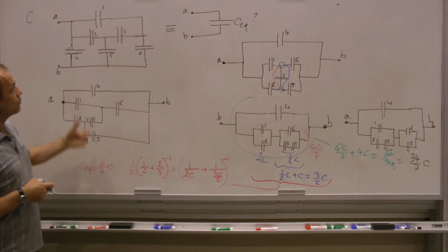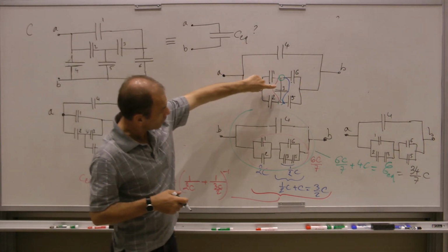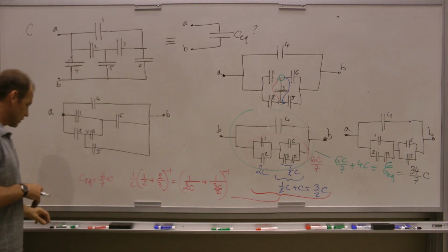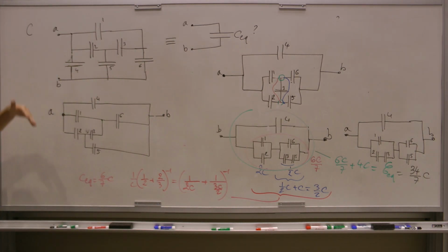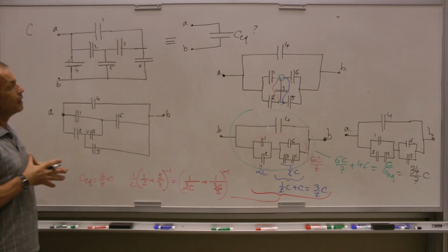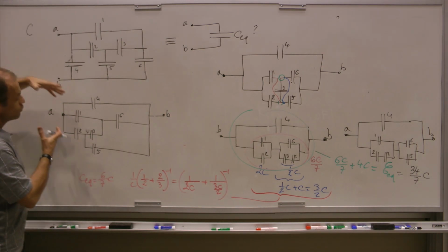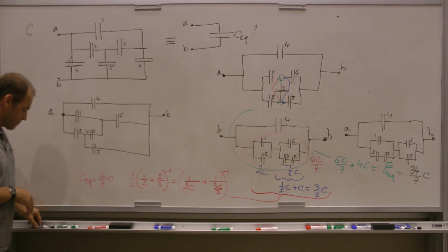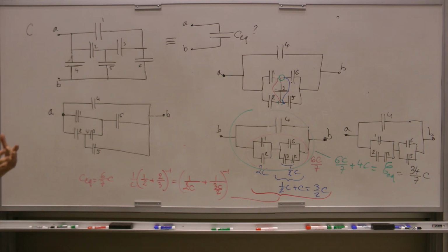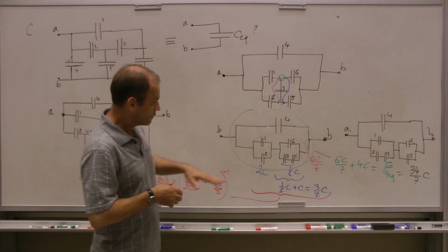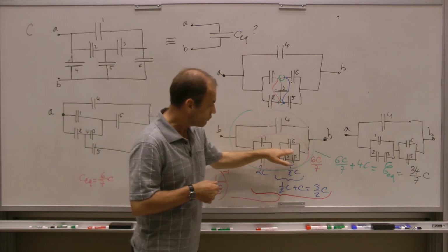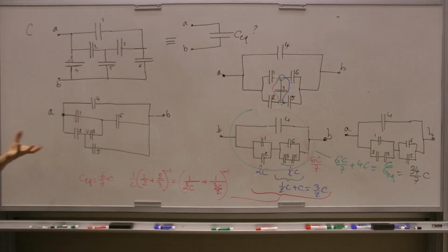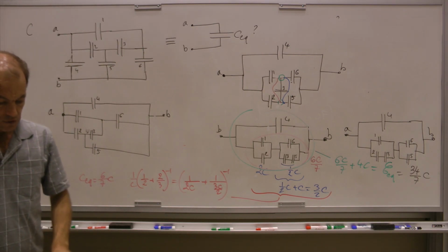So this was a little bit challenging because of the 3 capacitor right there, that capacitor number 3 connecting these two terminals, these two nodes of my circuit. But the principle is the same for any other type of arrangements of capacitors. You have to do multiple drawings to start to reorganize them in a way that's a little more amenable to basic calculations, i.e. bring them back down to something that we know how to deal, which is basic parallel configurations as well as series configurations. Something like that was kind of intractable to solve until you could resolve it in these very basic configurations.